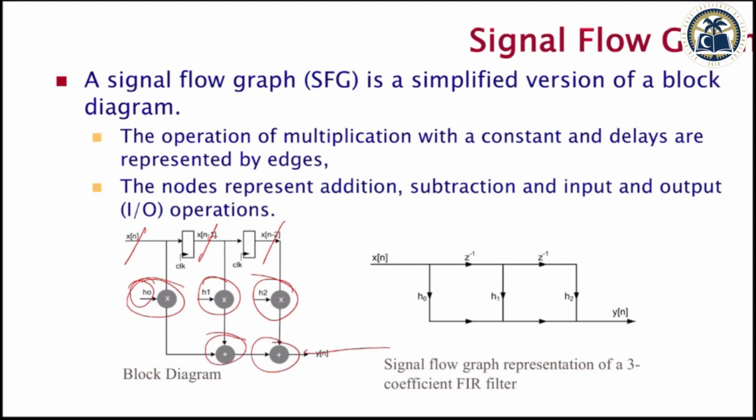So your every clock cycle and your analog to digital conversion clock cycle, they both are the same, running at the same clock rate. So every 500 megahertz you have a new sample, and every 500 megahertz this register also gets a clock, so it saves the value, does the processing and gives you the output.